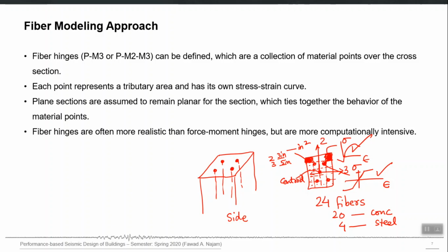So this is exactly what will be happening when you use the fiber modeling approach at the structure level, that you define a nonlinear material, define this kind of a cross-section, fiber cross-section or fiber section for all of your columns, assign it to your columns and run the analysis. The program will be simply calculating the moment rotation curve for each of the elements in the form of capacity, and then demand also can be simply imposed or checked on that capacity.